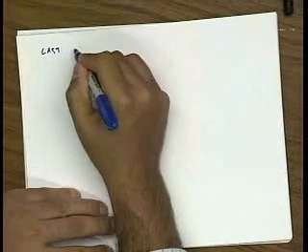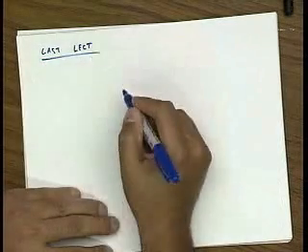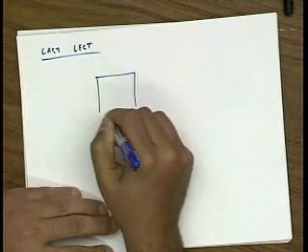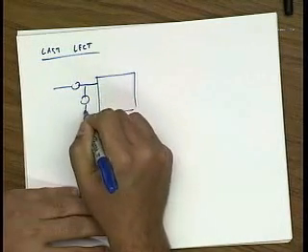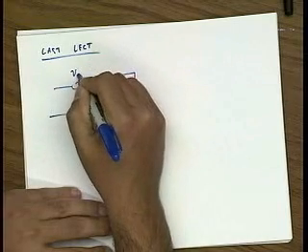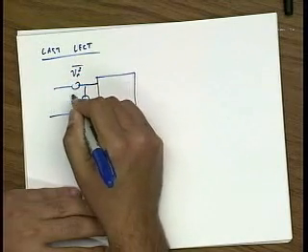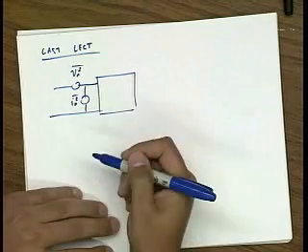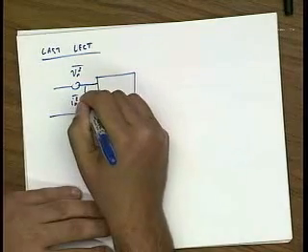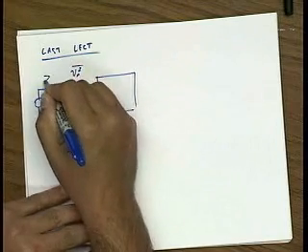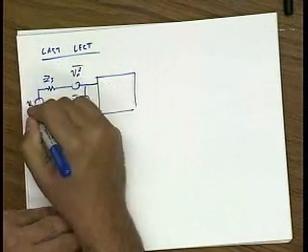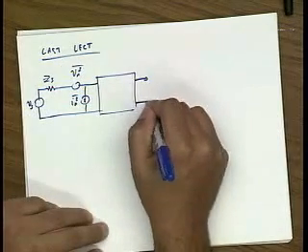Okay, so I wanted to pick up where we left off last lecture. Last lecture, we analyzed the noise figure of a 2-port circuit, where we made this simplifying assumption that the input voltage noise and the current noise are not correlated. I wanted to revisit that assumption and see what happens if we take that assumption away.